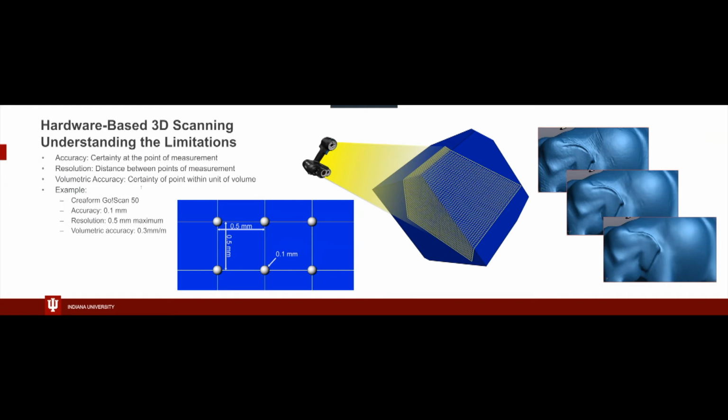What can happen when you crank up the resolution and accuracy of any of those methods is you start to get a sandy appearance. Imagine these spheres all bundled up against each other, with actual measurement points next to them. You're going to have a very sandy, rough surface. I tried to simulate that with the elephant over here. You can see it's a little sandy. This is 0.5 millimeter resolution, and then down here is 2 millimeter resolution. So you get more detail, but at the cost of it getting more sandy. That elephant scan is actually pretty good. I need to get a better bad example.